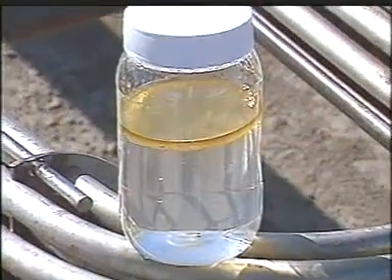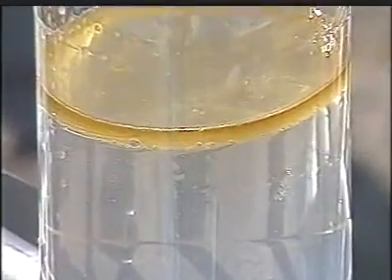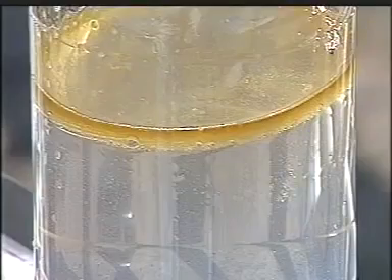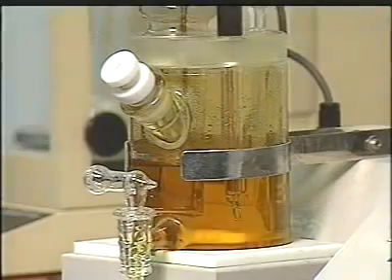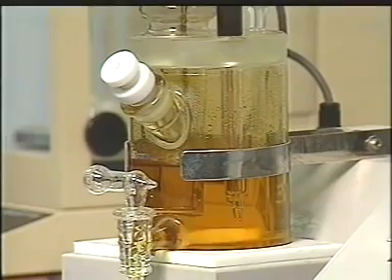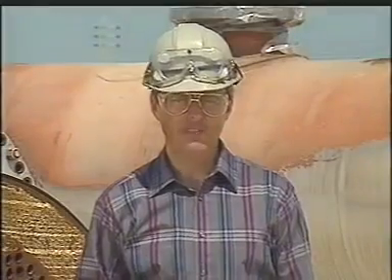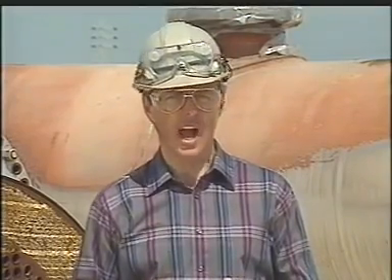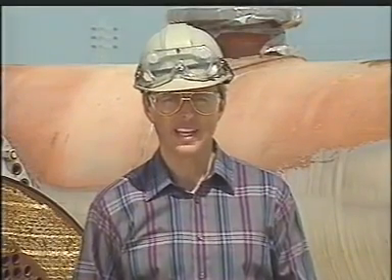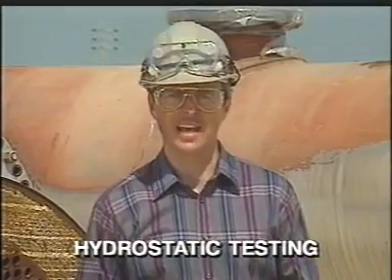This sample, for example, has a small amount of oil in the water line, a sure sign of a leak. However, if the fluids are very similar in appearance, chemical testing may be needed to detect the results of a leak. This must be done in the lab. If neither the visual nor the chemical tests are conclusive, a test using high-pressure water may be done. This is called hydrostatic testing.